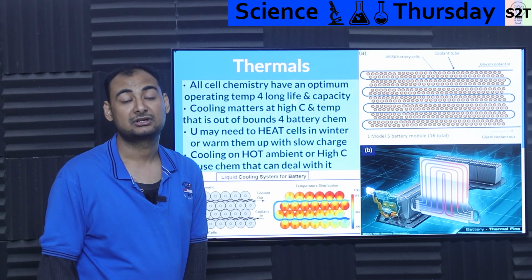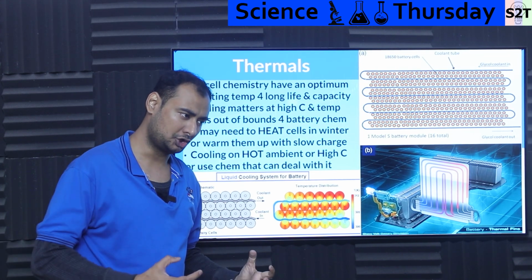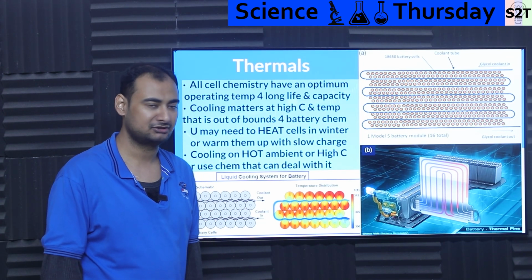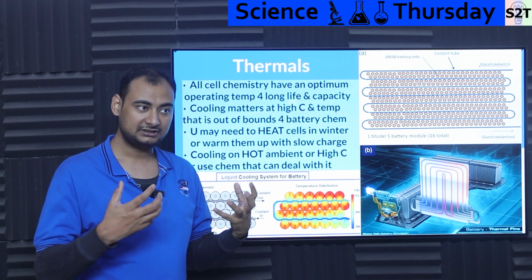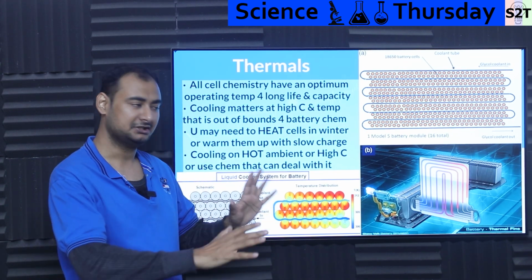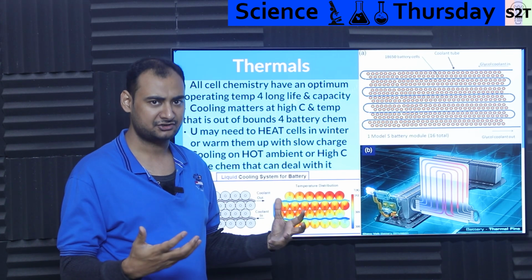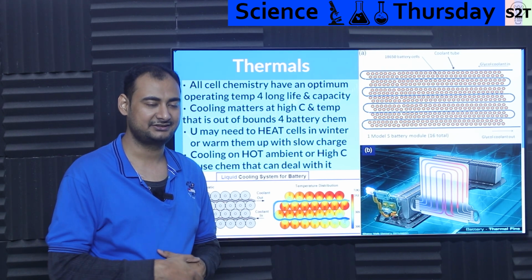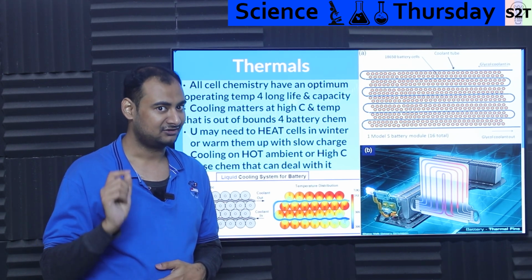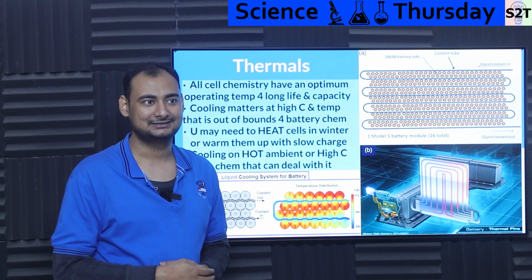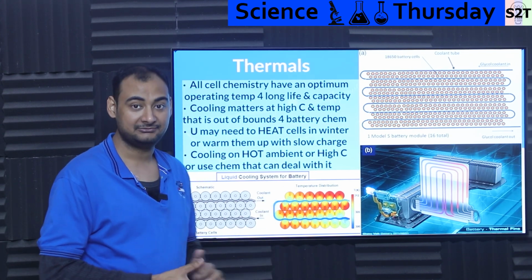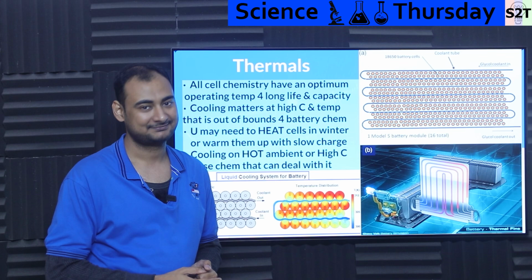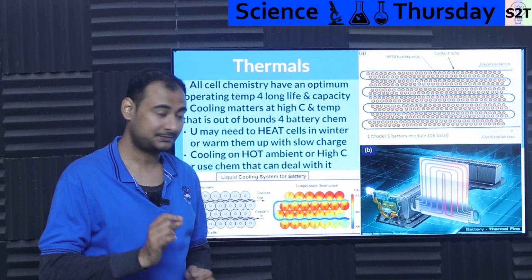Now, cooling matters when you are talking about high C loads, meaning if you are ultra charging, like I'm going to charge my car at like 250 kilowatt. Yeah, it needs a bonkers amount of cooling. And that's during charging and also during discharging. People like the idea of having electric cars that can go 0 to 60 under 2 seconds, and that's a lot of amps that your battery is draining. And again, batteries are resistors, they are not capacitors. They do heat up a bit. If you do not cool them at that point, they will degrade. Now again, if you are lucky, they will just degrade. If you are unlucky, they will catch on fire. So cooling matters a lot, especially if you are having high C.